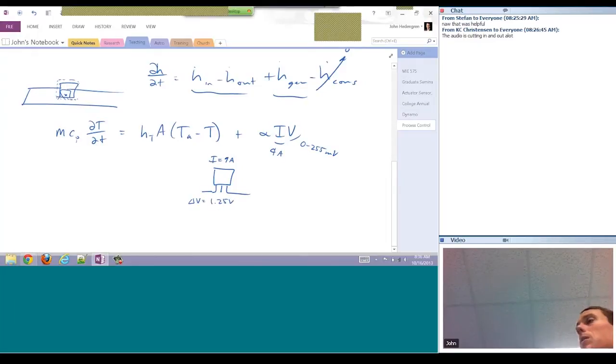So a transistor is actually trying to be like a switch for something else, to turn on or off another device that uses a lot more power. A perfectly efficient transistor would have no voltage drop across it. It's trying to deliver power to something else. It's like a light switch. But there is a little bit of voltage drop across it, and that's why it heats up, and that's why we can use it for this lab.